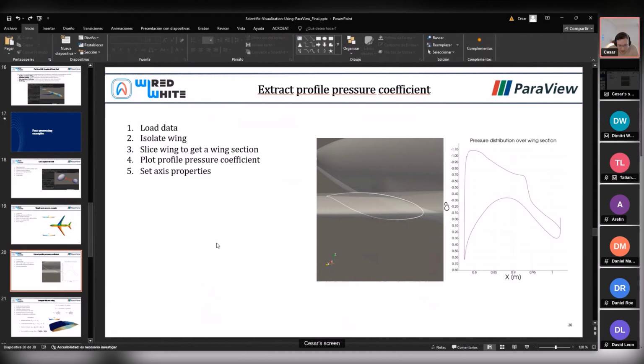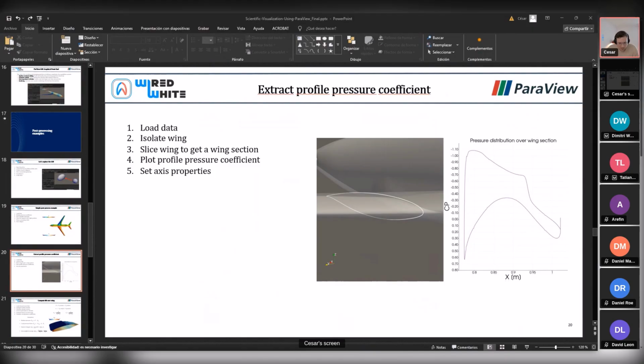How to export simulation data directly from Fluent to ParaView. Okay, in this case, I use Ensight a lot. With Fluent, you can generate Ensight files, and ParaView can open these files. I think the format is called Ensight Gold. So try it, and it should work 99%.